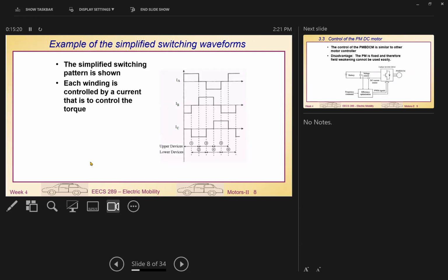So in this waveform, you can see that each of the phases A, B, C is displaced by 120 degrees from the next phase. Because in a three-phase motor, each of the phase voltages or currents will be displaced by 120 degrees anyway. So that's why we use this method. If you study more, then we have the pulse pattern to drive them. So we turn on transistors 1, 3, 5, 2, 4, 6 in this manner.